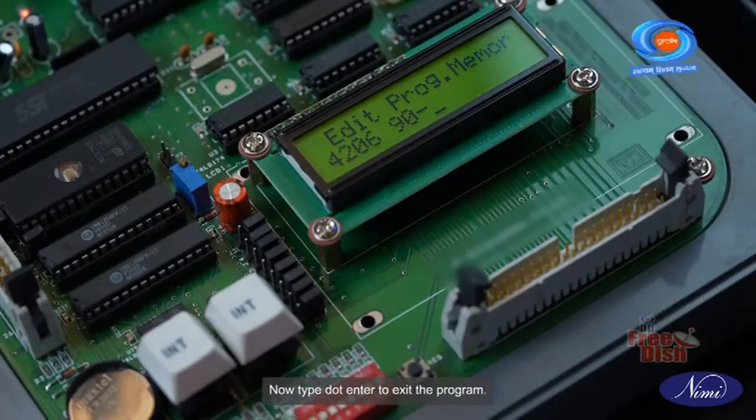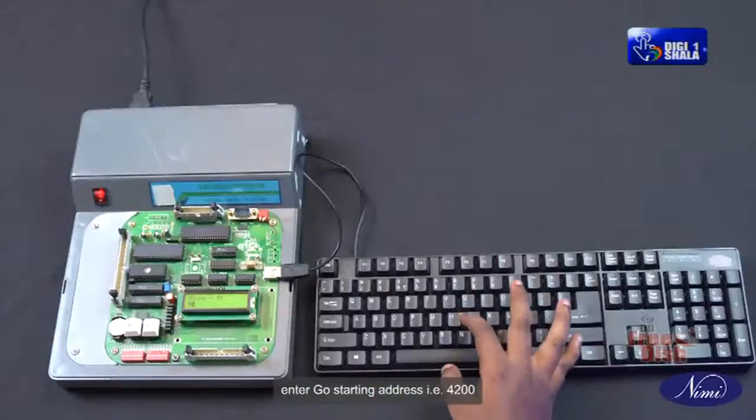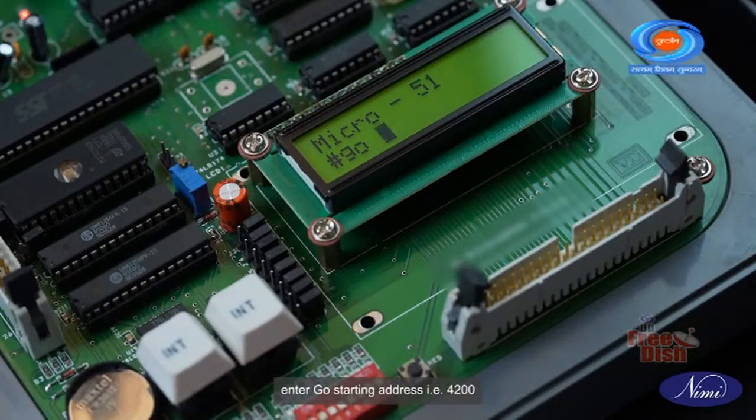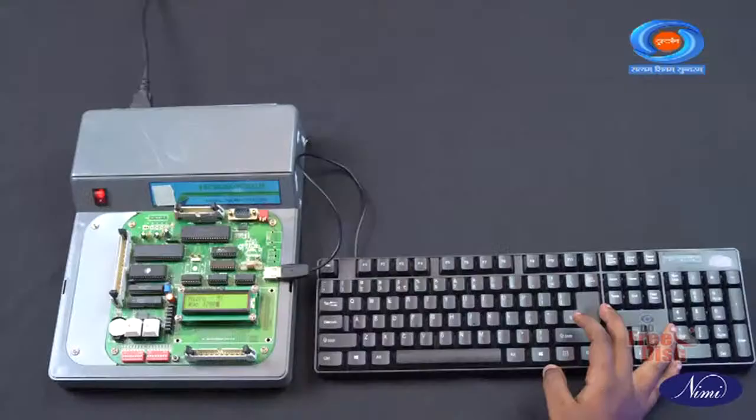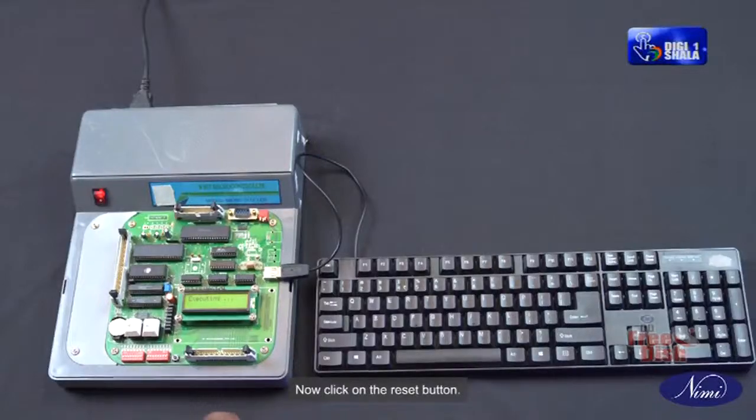Now type .enter to exit the program. For executing the program, enter Go, starting address, that is 4200, and click enter. The display will show executing. Now click on the reset button.